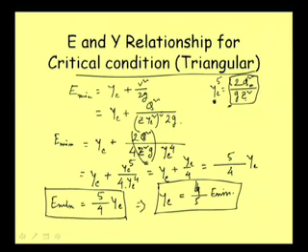From these two analyses we could see that for triangular channel and for rectangular channel we can express minimum specific energy, that is the energy at critical condition, in terms of yc. Now, if it is a parabolic channel, let us see what sort of expression we can have, or can we solve critical depth directly for parabolic channel?